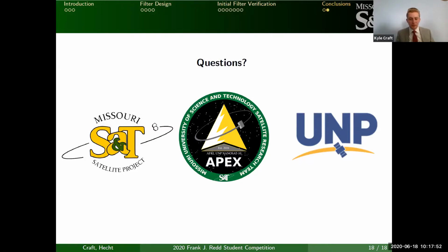Is the proposed filtering method sensitive to thermoelastic distortion of structure and/or resulting changes in alignment of the star tracker, satellite reference points, etc.? So we're not modeling the elasticity of the structure, but we do, in the consider parameters for the attitude state, include the biases from misalignment and thrust vector misalignment. So for the star tracker and for thrust vector misalignment.